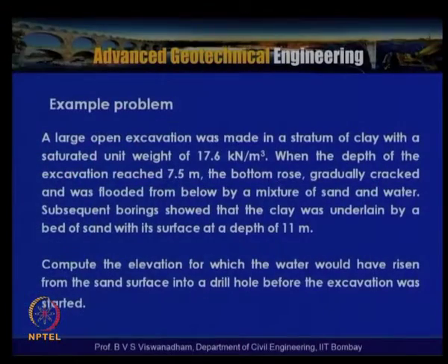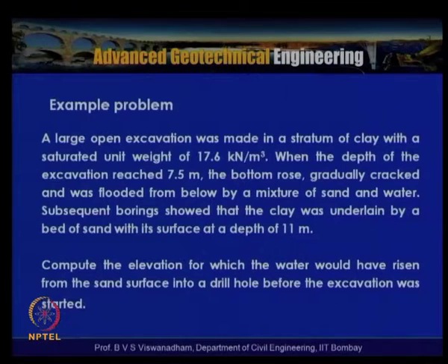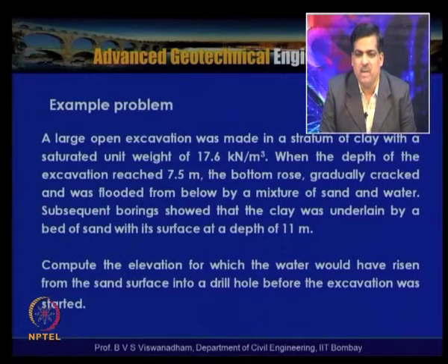Another example problem, relevant to field conditions: a large open excavation was made in a stratum of clay with a saturated unit weight of 17.6 kilonewton per meter cube. When the depth of the excavation reached 7.5 meters, the bottom rose up, that means heaving of the bottom took place, and it gradually cracked and flooded with a mixture of sand and water. Subsequent boring showed that the clay was underlain by a bed of sand with its surface at a depth of 11 meters. Compute the elevation to which the water would have risen from the sand surface into the drill hole before the excavation was started.